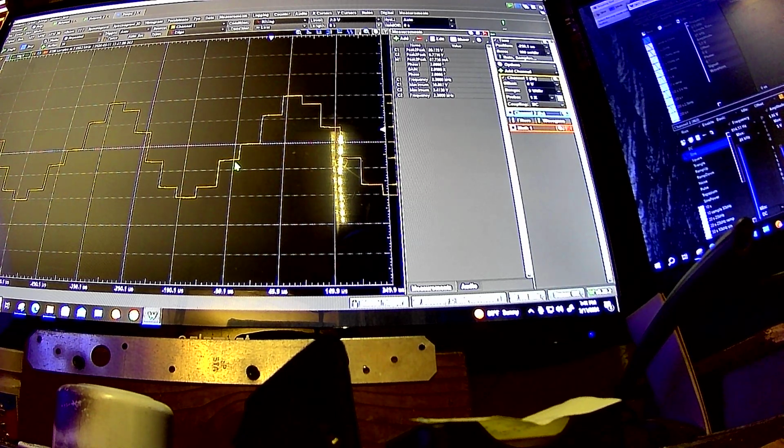So it just helps having a video like this so you can actually put things in perspective if you're thinking about working with DACs. As far as what kind of realistic frequencies you're going to get out of the thing and what kind of actual resolution you're going to be able to realize. Because again, the DAC I have is a 12-bit DAC, and that means it can do 4096 levels.